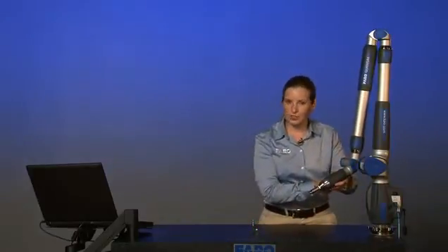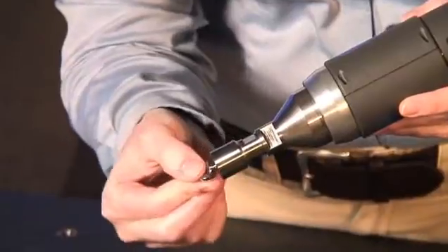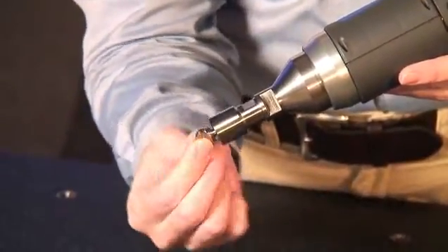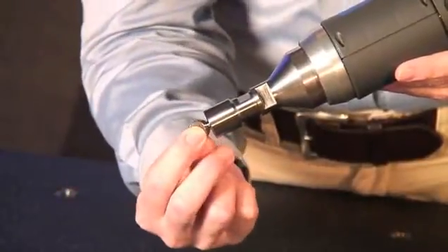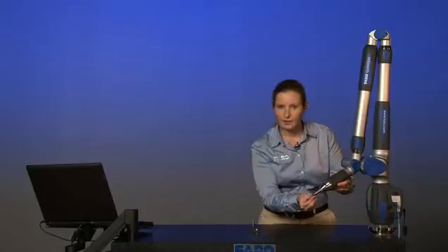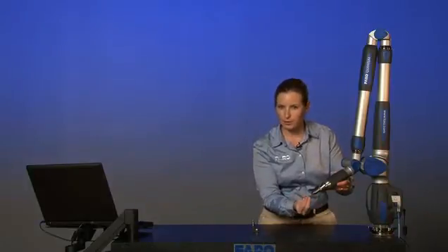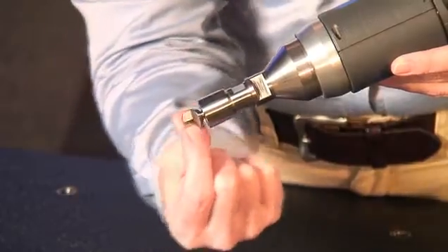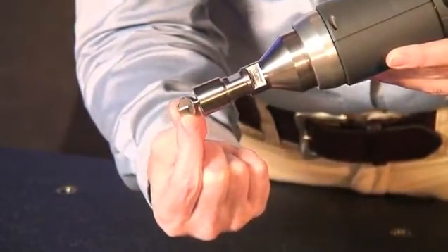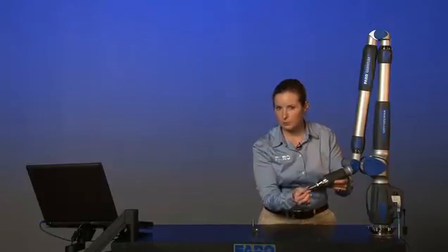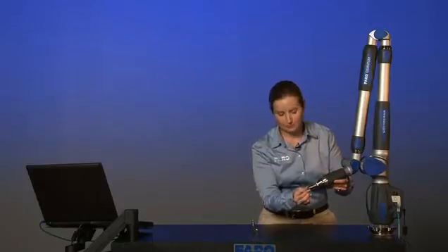What we have attached to the end of the arm is a swivel probe, and this particular one, you can see that the ball pivots on the end of the probe and it has a cutout in it. And the cutout goes exactly to ball center. So as you're gathering data, your part is going to ride at the middle of this probe to capture your data. And there's no need to adjust for the radius of the probe after you capture that data.